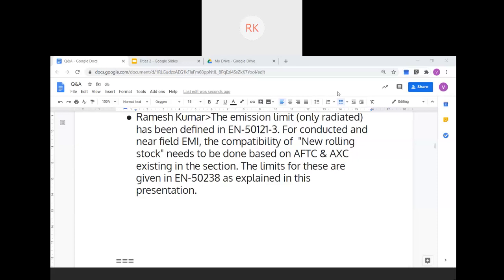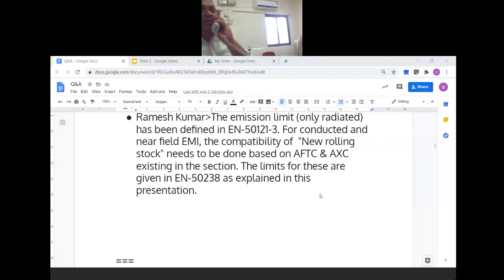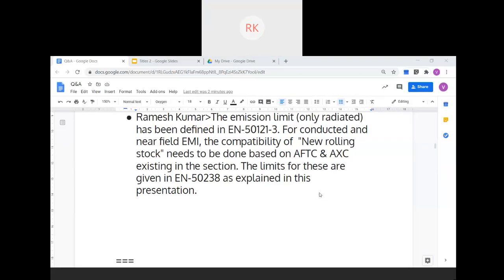And plus, right now, I think RDSO may have done it. I'm not sure. We will have to clearly have a sign off with the rolling stock manufacturers, Indian Railways, all our RCF and all these people, that earmarked space should be provided for future signaling equipment. And we had a lot of problems. WAP5, the space was given, but when we went and saw it at the site, they were different for every locomotive. Second, the control cables that were running to the traction motors, the idea was all the electrical control cables would be on one side. Our data cables will be on the other side in the undercarriage. That was also not respected.